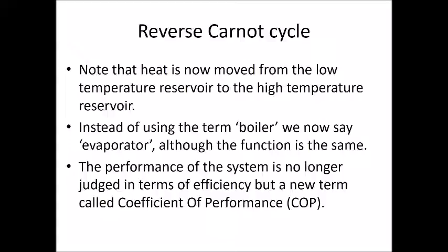So the amount of work required for the pump to pump a fluid containing a certain amount of heat isn't really a function of the amount of heat that was in the reservoir. So if we do it right, we can pump a hell of a lot of heat only using a small amount of work. And when you do the theoretical calculations based on the refrigerants and the enthalpies, just like we'd normally do for a power station, what we'll get is a value much greater than 1.